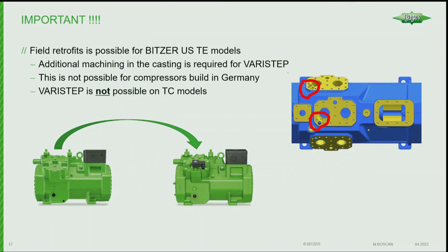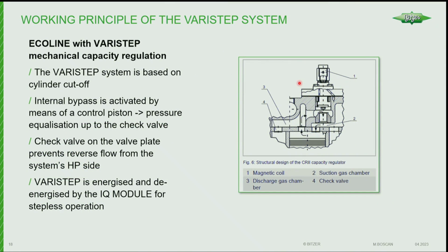Okay, so how does mechanical unloading work for a CO2 compressor? It's basically the same thing, right? So the first line is it cuts off the cylinders. So under each cylinder head, there's 2 pistons. On a 4-cylinder, when you unload it, you're killing the mass flow through those 2 pistons. They move up and down, but there's no compression happening, and that's how you unload our HFC compressors, and that's how this ends up unloading as well.